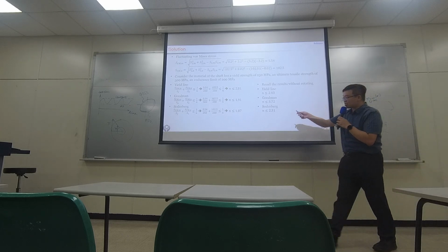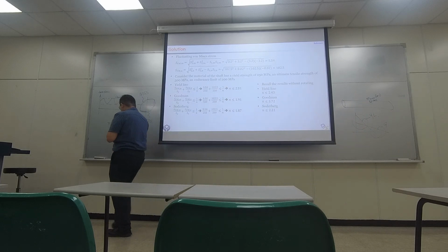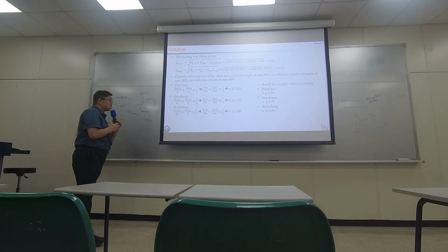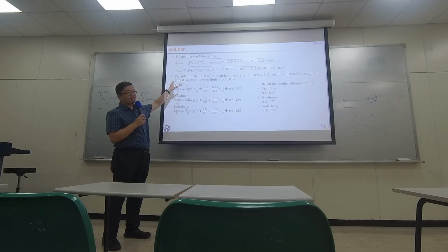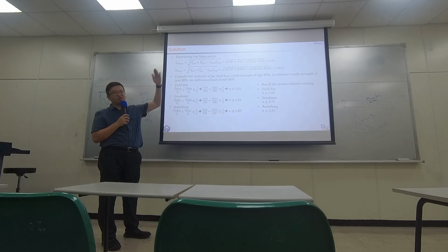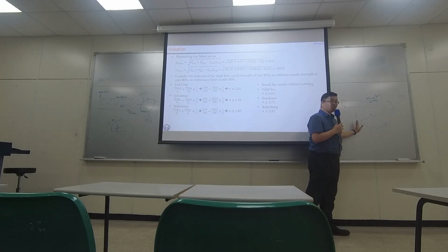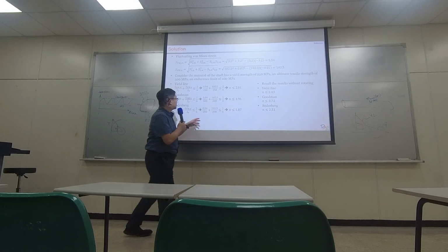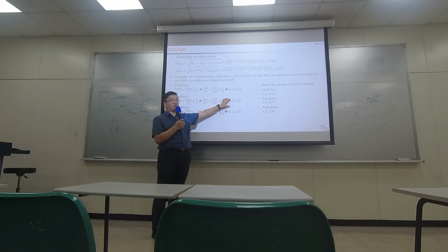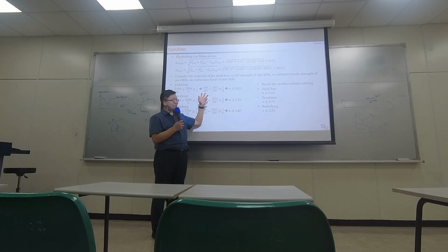So from here, just like what we have found, in this second example, we have a stronger amplitude part. So our design point is somewhere closer to the vertical axis. And our design point is having more serious issues on the amplitude part. That's why Goodman is showing a lower value of safety in this particular problem.